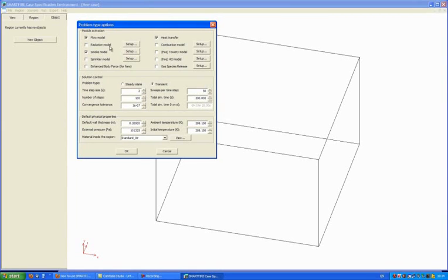Activation of the radiation model will be required if you have a lot of fuel that will burn or a high heat release rate, because radiative heat transfer will become a large mechanism of heat transfer when you have very high temperatures involved. So these sort of choices need to be made at the start so that all of the objects can be configured correctly.